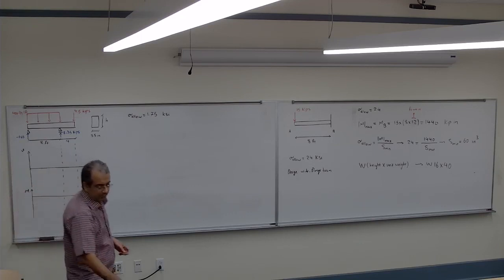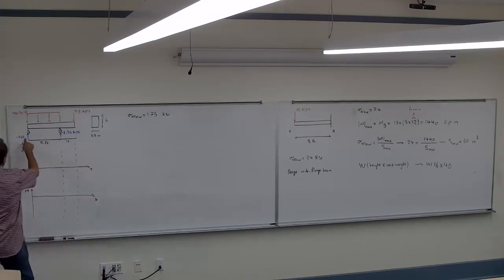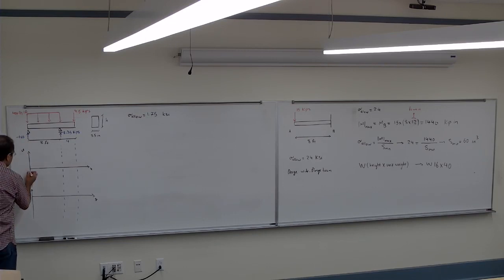So if I start with the shear, the concentrated load is negative 0.65, so I have to start from negative 0.65. That's where I started, but I pushed it down. And then I have the distributed load that is also pushing it down. It's constant, so it's gonna push it down linearly. So the amount of that is 400 times 8.